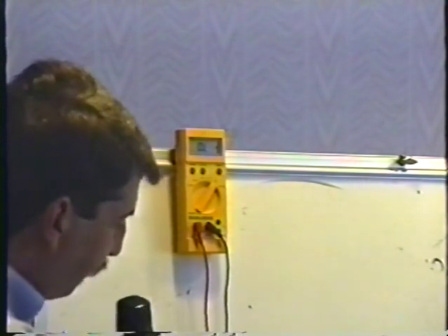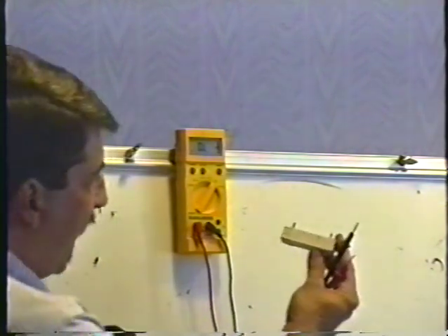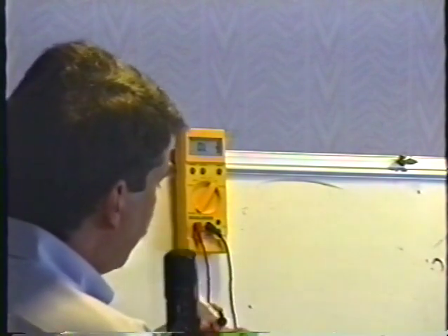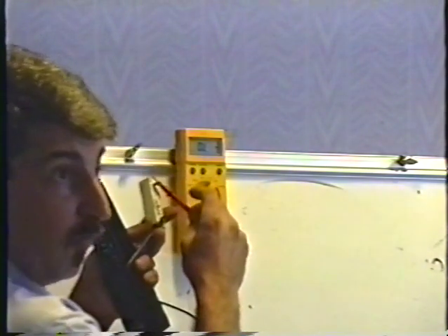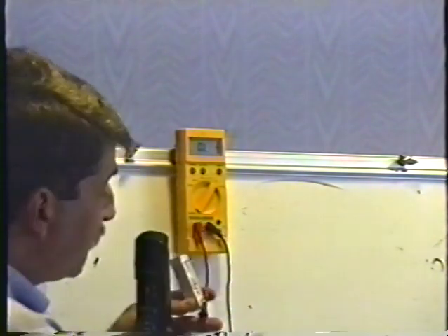This one is a humongous resistor. This is an 80-watt resistor, gigantic thing, 330 ohms, 80 watts. When I put my meter leads across it, nothing. The meter shows me infinite ohms. It doesn't change at all. Obviously, open resistor. So this is what resistors do when they fail: they open circuit.